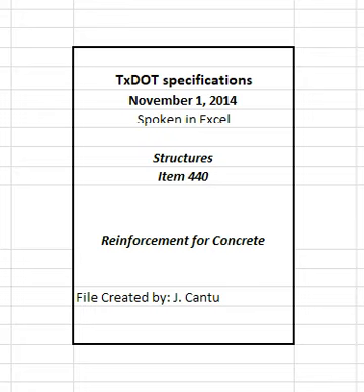Fabricate in the shop if possible. Field fabricate, if permitted, using a method approved by the engineer. Replace improperly fabricated, damaged, or broken bars at no additional expense to the department. Repair damaged or broken bars embedded in a previous concrete placement using a method approved by the engineer. Unless otherwise shown on the plans, the inside diameter of bar bends, in terms of the nominal bar diameter, D, must be as shown in Table 5.